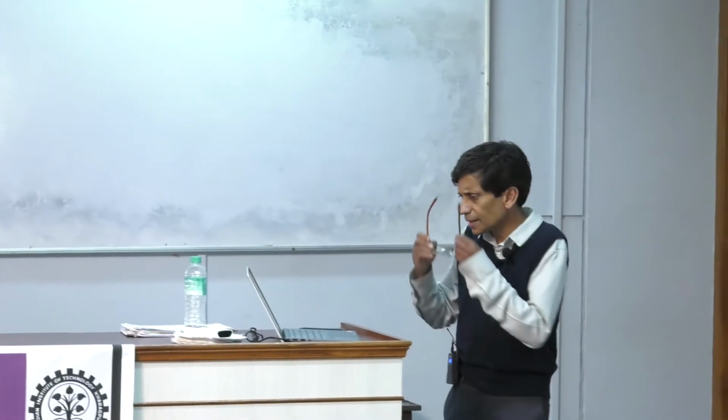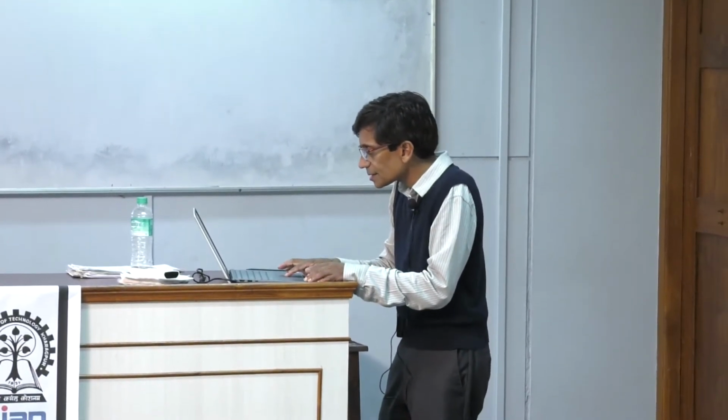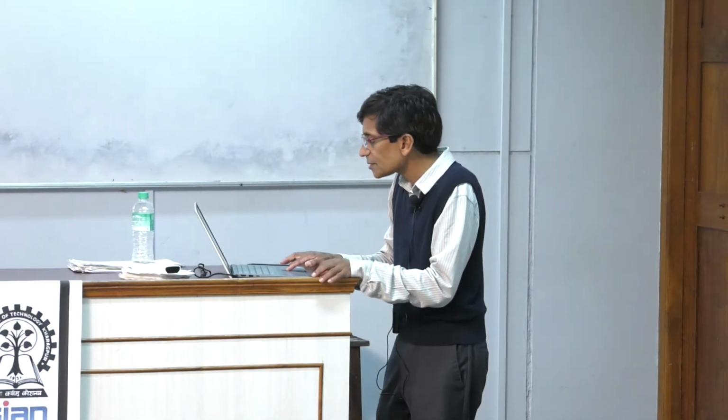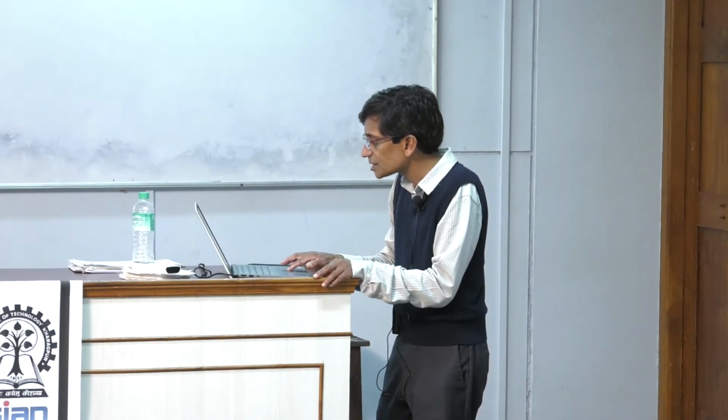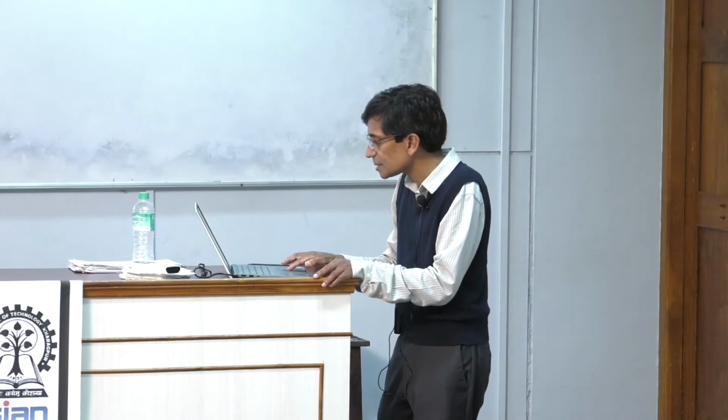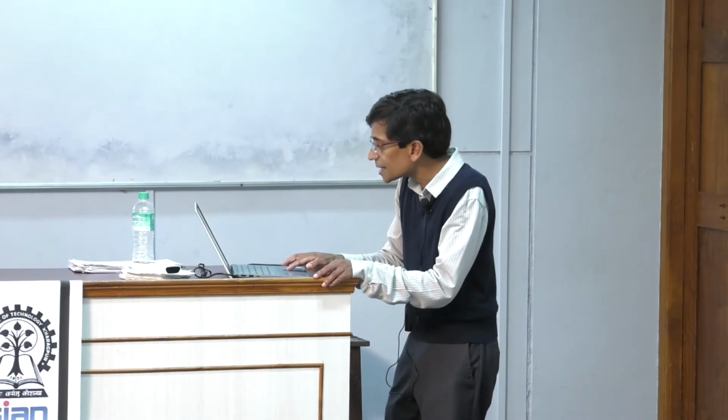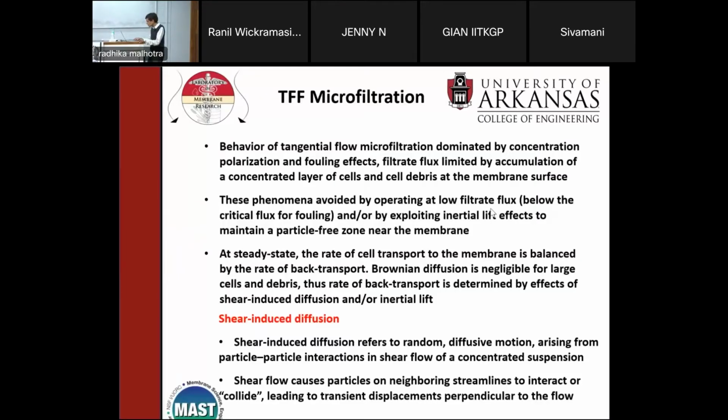And so I said here, concentration process fouling effects: filtrate flux limited by accumulation of a concentrated layer of cells and cell debris at the membrane surface. These phenomena are avoided by operating at low filtrate flux, below the critical flux, and/or exploiting inertial lift effects, to maintain a particle-free zone near the membrane surface.